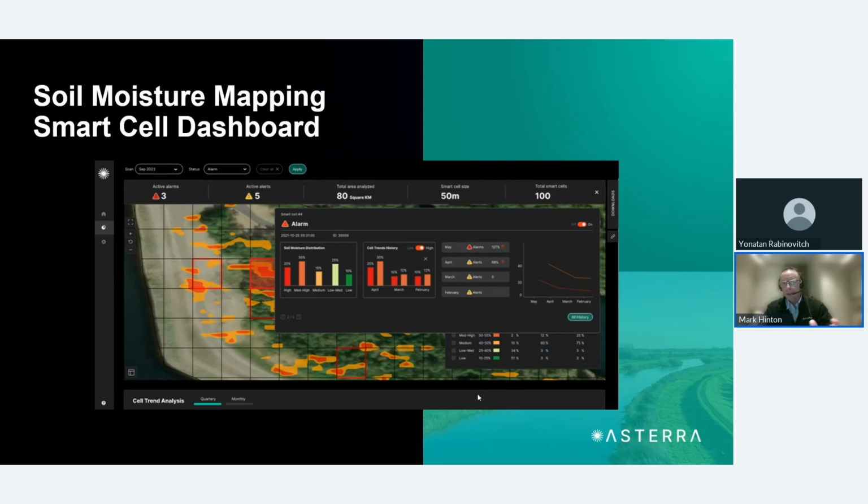We can also report it in a way that you can pick up trends. So even though you might not have hit a threshold, you might be trending upwards in a way that you want to know about, and we can pick that up as an early trend. For a dam structure, for example, that type of build-up of moisture can be indicative of progressive seepage failure, and you can potentially pick it up in its very early stages. So slope failure or drainage performance issues are all use cases where soil moisture build-up anomalies and patterns can be important.